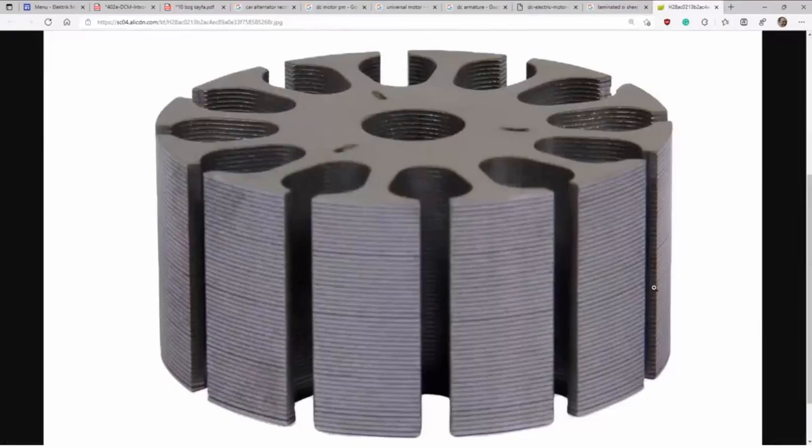That is the main magnetic part of the rotor. This material is silicon steel sheet material. Sometimes we say laminations because each silicon steel sheet is isolated from the others by a tiny insulation layer. I mean varnish.